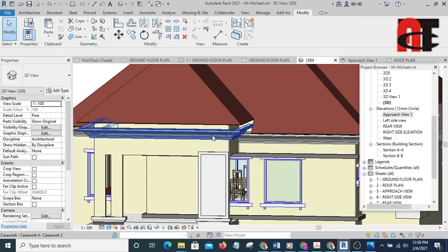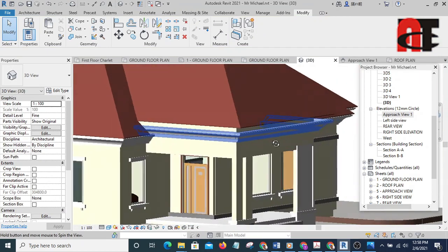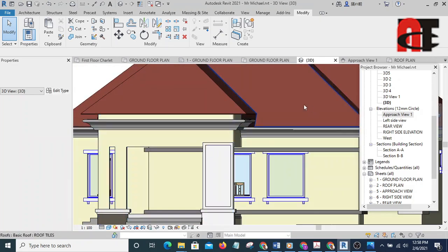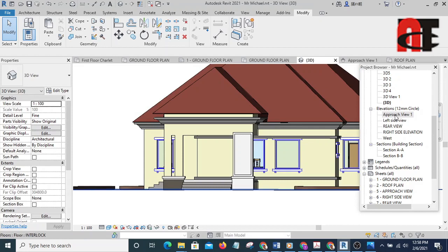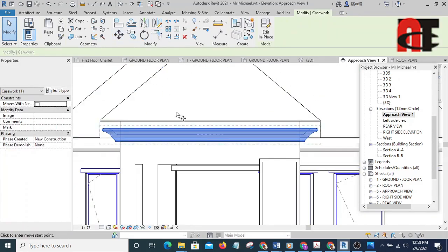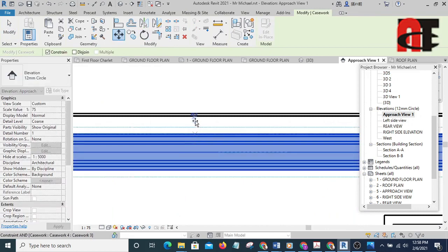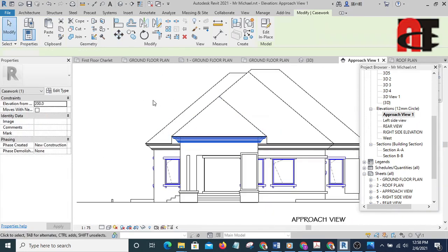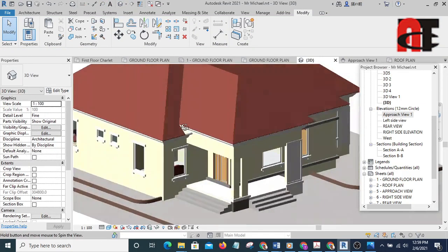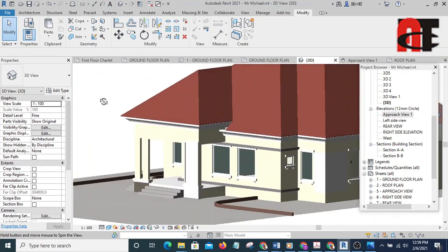Okay, so this one is the part for the elevated part. So I'm going to move that up as well. I will go to elevation and move it up. I'm going to uncheck constraint, then disjoint so that it can move freely, otherwise it will not move. Let's look at it in 3D. All right, here we go. Smooth.